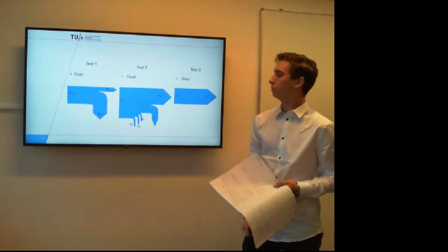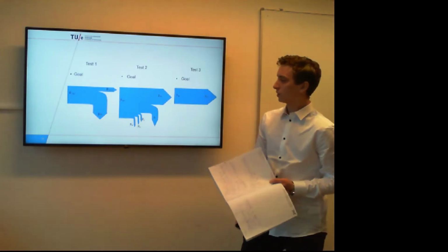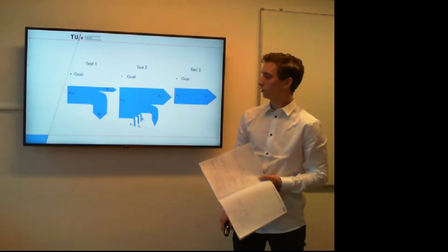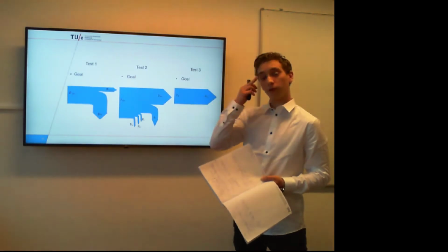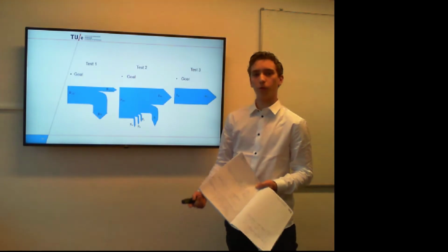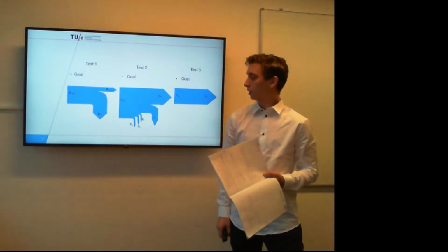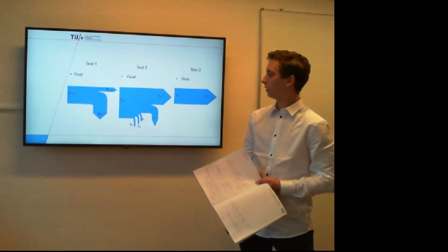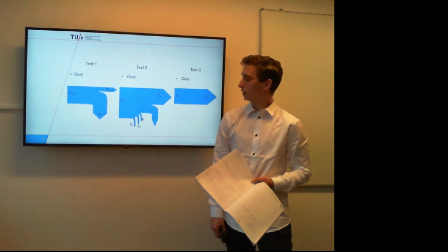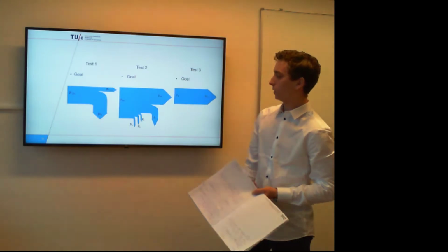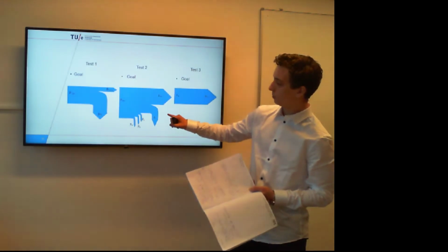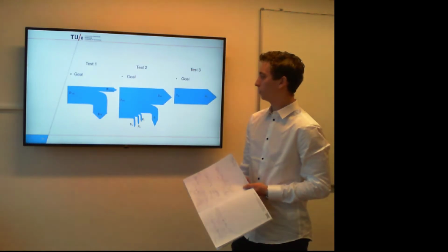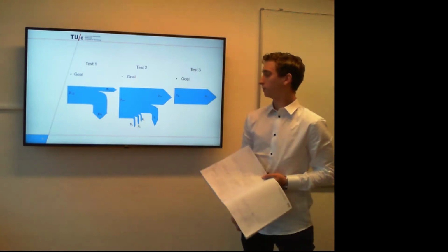Then we've done test 2. In test 2, we wanted to calculate the overall P in and P out. So we measured the P in, the power from the motor, and that's also the power we put in via the battery. Then we've also measured P out, and that's the power of the dyno, the power we measured at the dyno. With this we can make a general calculation of how big the total amount of resistive force on the car will be.